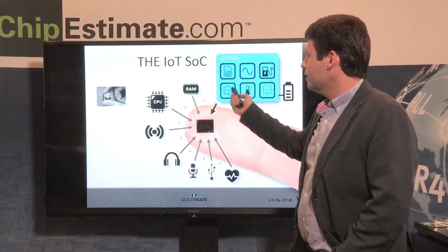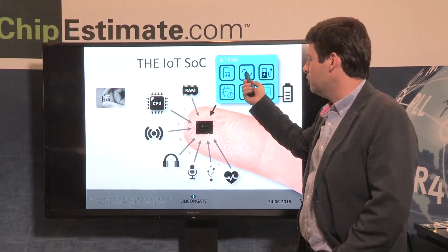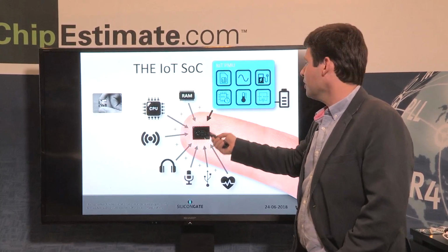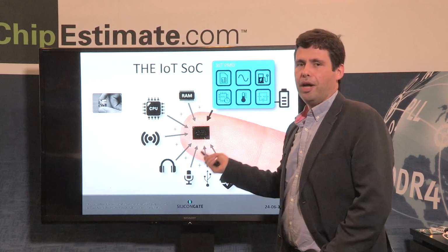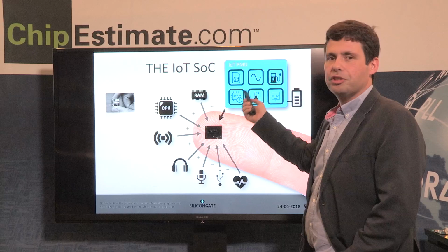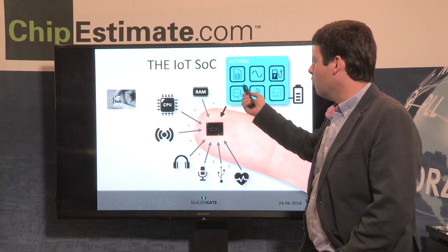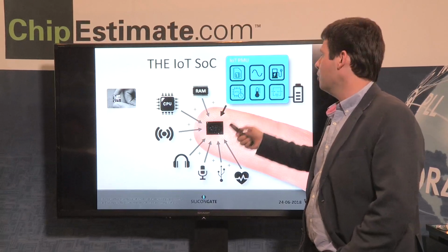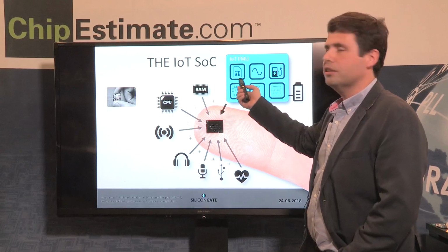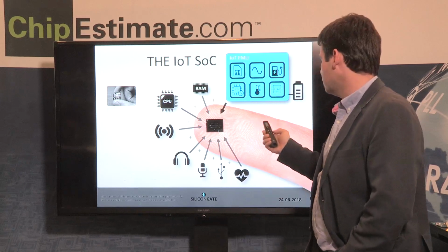The RTC ends up being a backbone for the PMU that is used on IoT. The PMU on IoT is basically a PMIC that fits within the system on chip, the SoC, and that solves all the supply problems. We're going to talk about that later on. The RTC is that backbone that allows the system to have very low power modes, and then the RTC will keep all the functions that need to be alive all the time and wake up the system whenever it's necessary. So things like interrupts and real-time clock and alarm, all that is inside the RTC, and I'm going to explain that later.